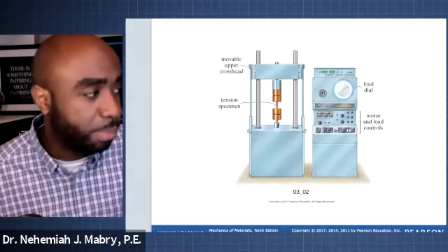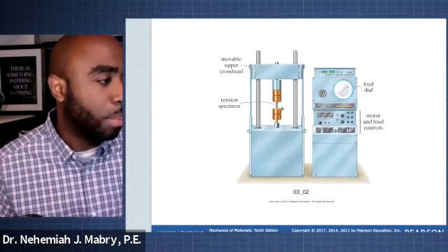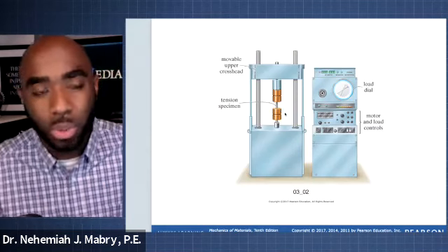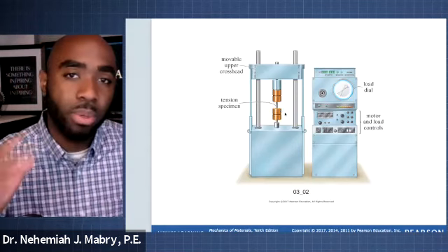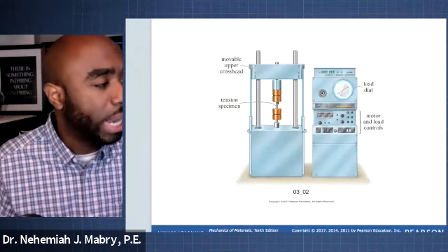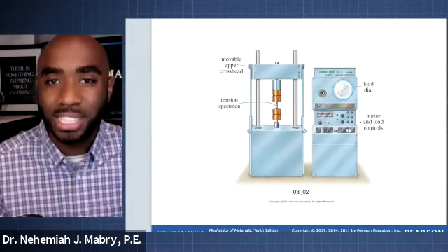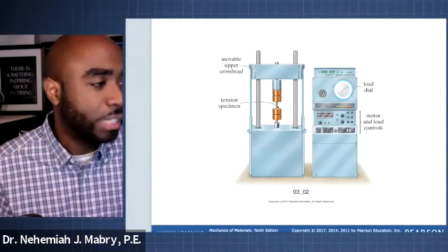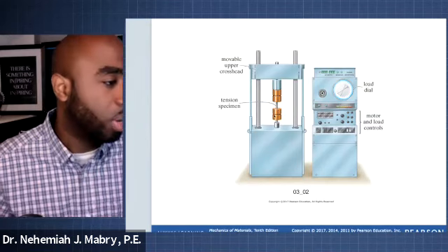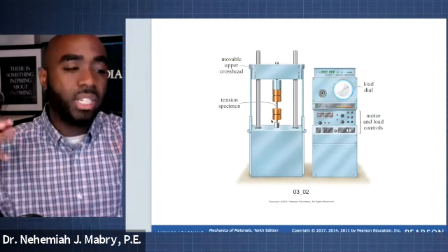As I showed you before, it is attached to the side of the specimen. That specimen is put into a tensile testing machine here in the middle of this device. If you ever went to a structures lab or materials lab, you would see this. This upper head begins to move and apply tension to that specimen. As that specimen experiences tension, we're tracking the change in the strain.